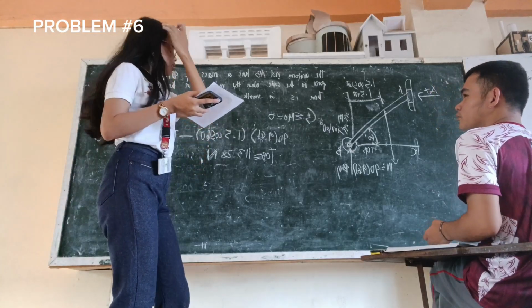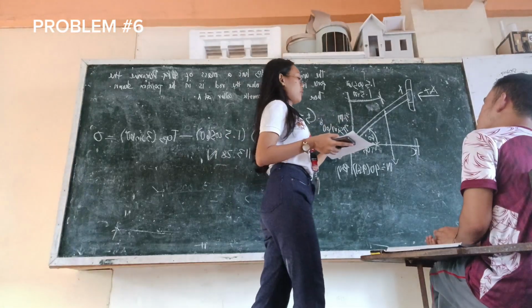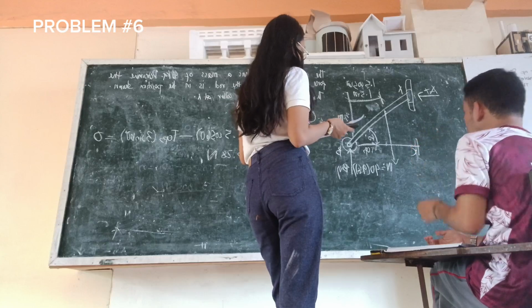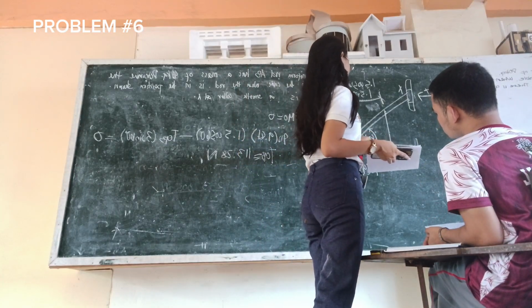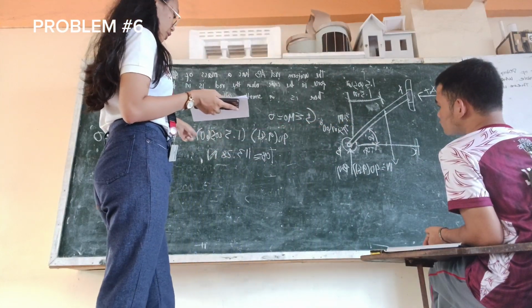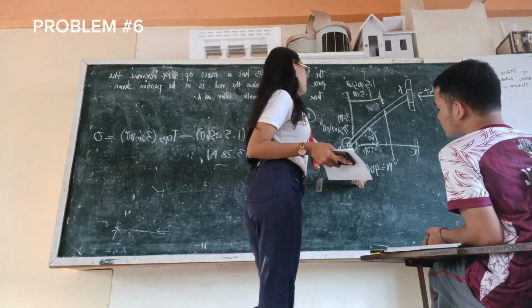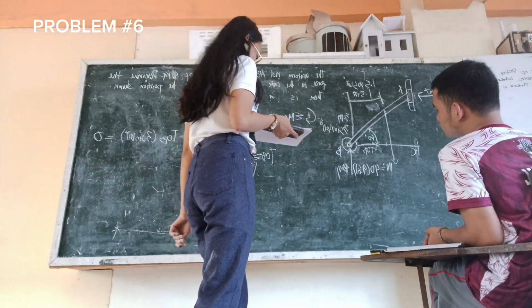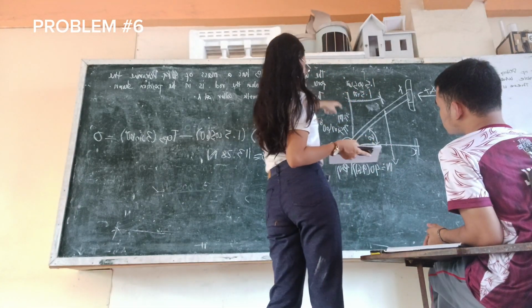So the only forces that are going to create a moment, as you can see here in the free body diagram, will be the W and the tension, which is TCB. So first we are going to find the moment arm of the W, which is 40 times 9.81, and then the distance, which is 1.5 cosine 60 degrees, and